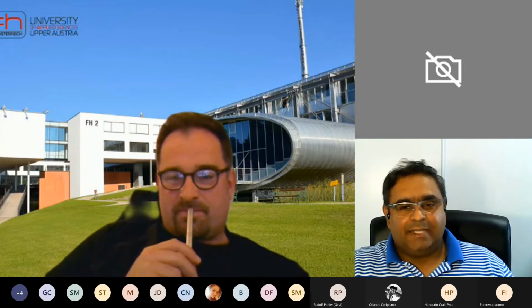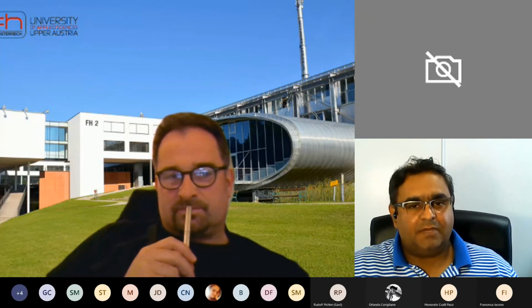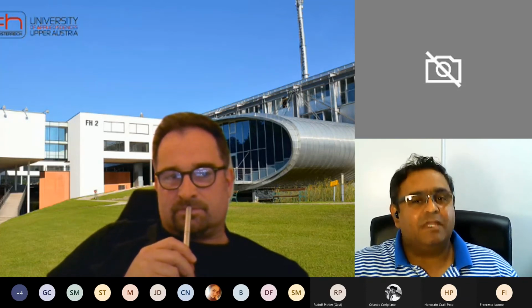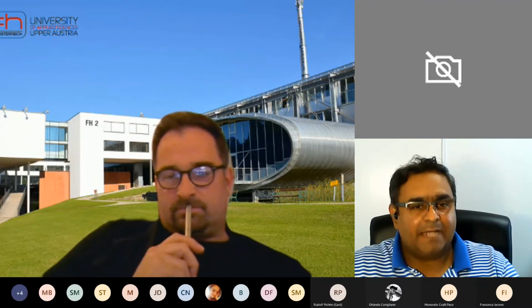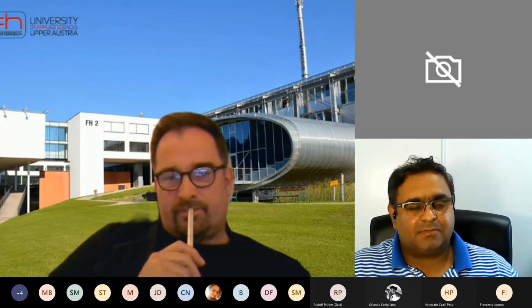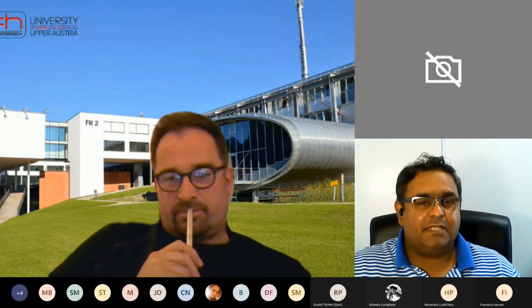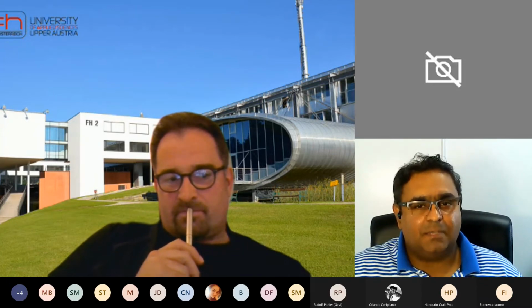So let me share the model. We just gave the forces and the location of the forces on the model. If we go for every part of the crane, that will be so extensive and will really take so much time. So our concern was the final forces on the mat. That's why we just took major parts as one unit instead of giving small parts separately. So it took us less time because we just combined them.